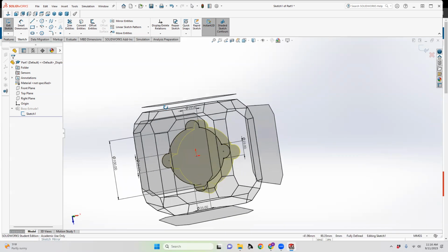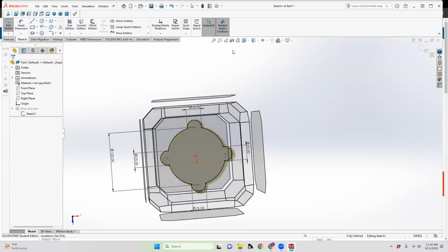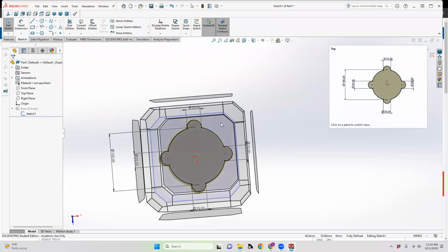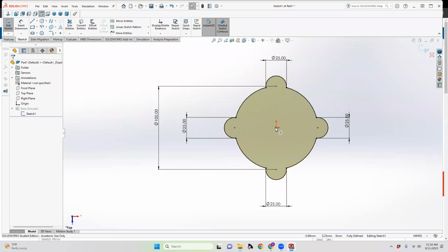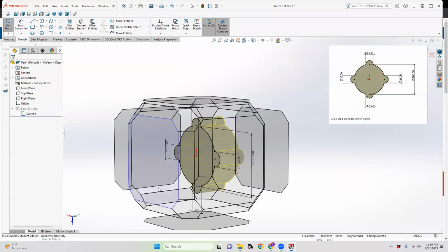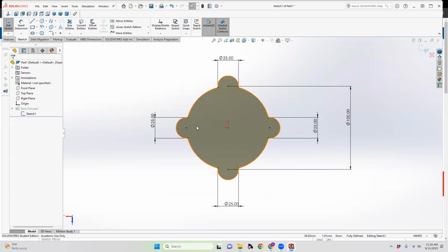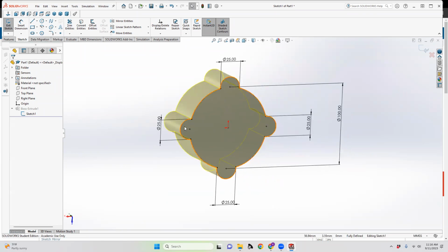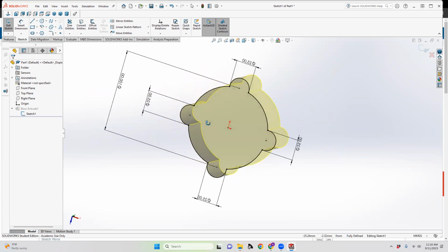I always recommend when you're doing a sketch, you want to look straight on. So what you'll do is you'll select this. And in this case, we're going to select that top because that's going back to our original. If you select on the bottom face instead, what that's going to do is change the direction of some things, and that can mess with you if you're trying to do some specific references and extrude cuts into something. So there's a lot of things that we'll have to learn in terms of fundamentals.